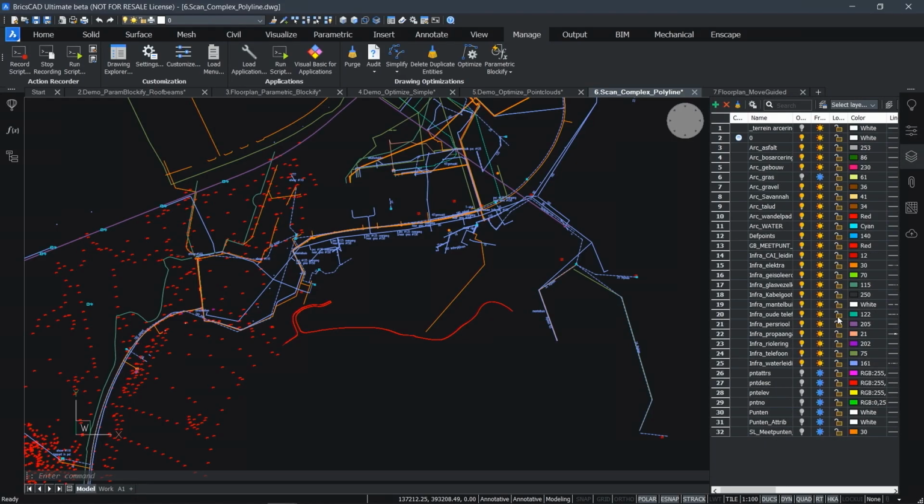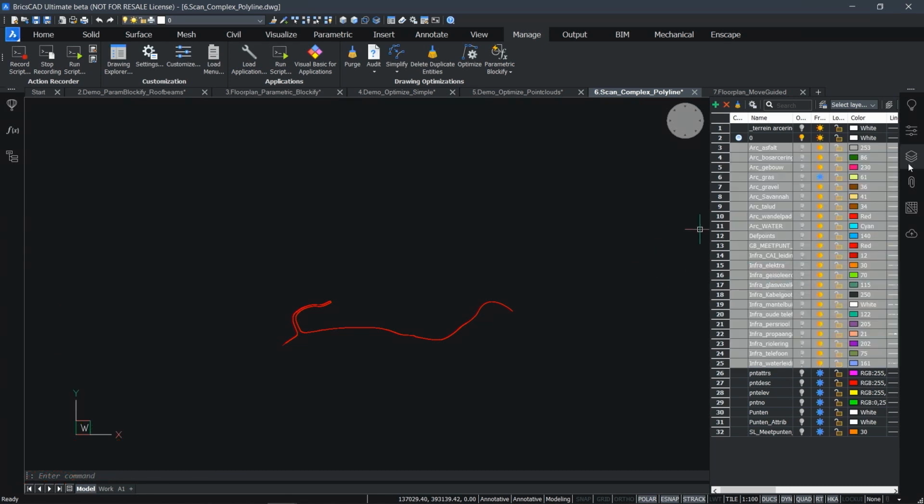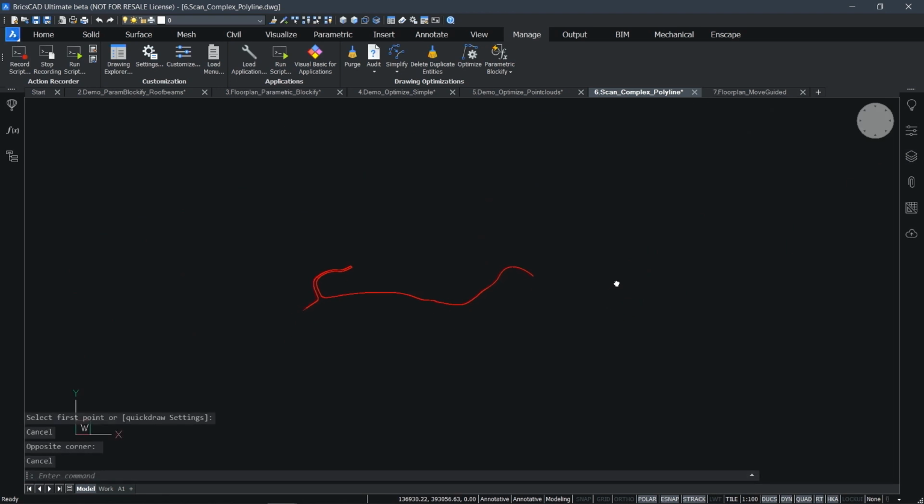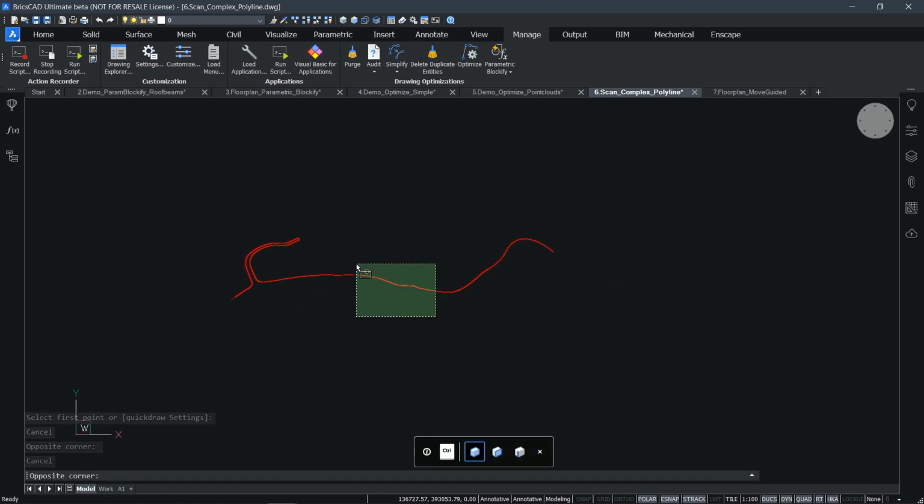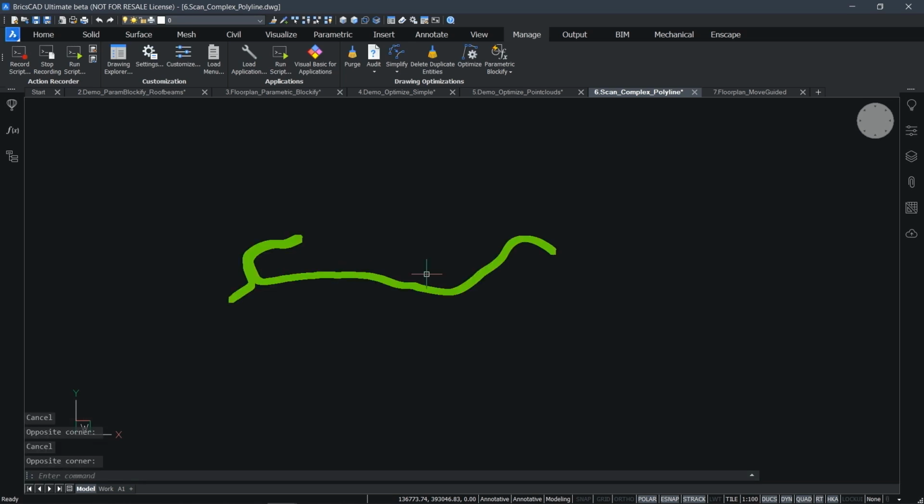The number of drawings originating from scanning devices is increasing rapidly. But typically, we see that these kinds of drawings contain way too much detail to handle in a double precision CAD system like BricsCAD. For example, let's have a look at this scanned map. When we hide some of the layers, we retain only one entity, this polyline. It is a part of the boundary of a lake, which only spans 340 meters, but it contains more than 350,000 vertices. So it makes it very hard to handle.